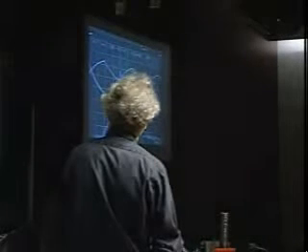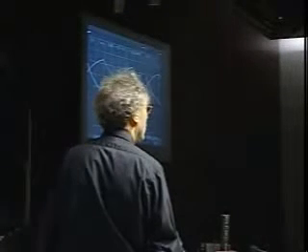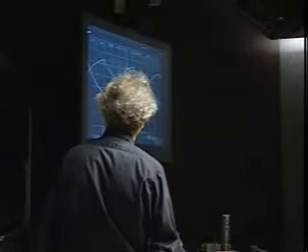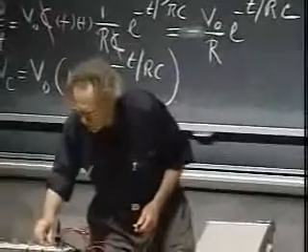Notice also that the current doesn't reach zero for the same reason that the capacitor doesn't get fully charged. So it never reaches the point that the current becomes zero. I'm already switching here to position 2, and the current then flips over, but never becomes zero. All right, so let's go back to the 0.1 value. There it is.